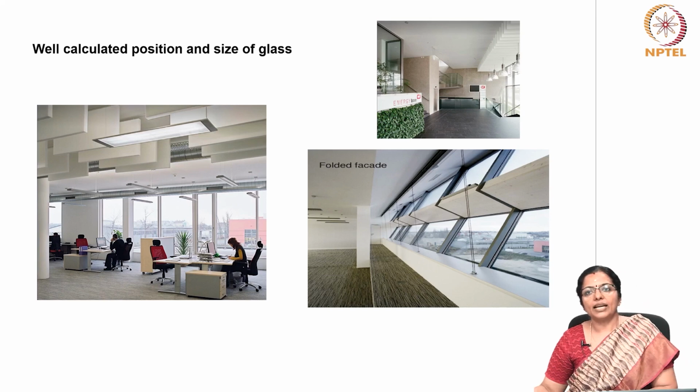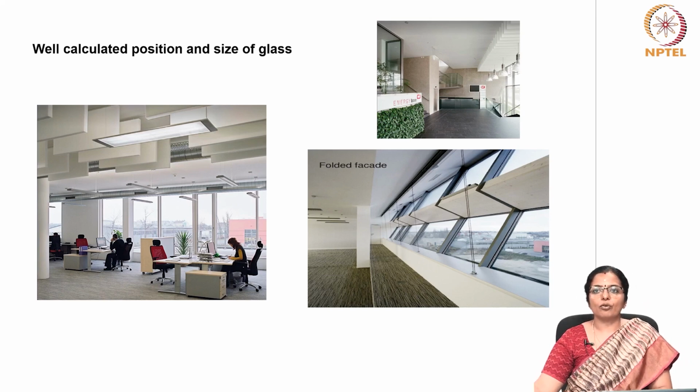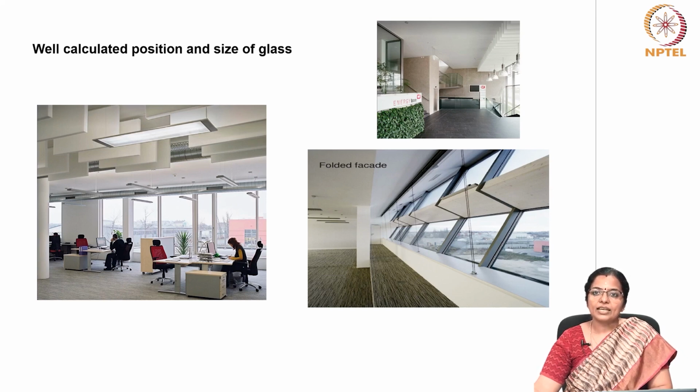In winter, the building combines solar preheating of ventilation air with heat recovery in a very different way. Ventilation air flows laterally from the north side to the south side of the building, then is overheated to the desired indoor temperature by the space next to the glazing, which functions as a solarium. This overheated air passes through the heat exchanger, where it is particularly effective in warming the incoming fresh air.